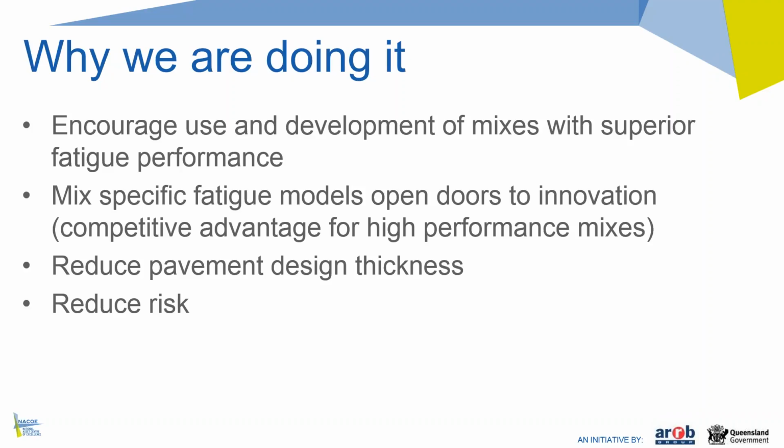And at the same time, I would again argue that this is reducing risk, because instead of using this general model that was developed for 12 mixes in the 1970s overseas, and those mixes have very little in common with mixes currently used in Australia, we're actually testing the performance of modern Australian asphalt mixes. And again, we're creating here a direct link between laboratory mix design and field performance. So this is a performance-related design method.